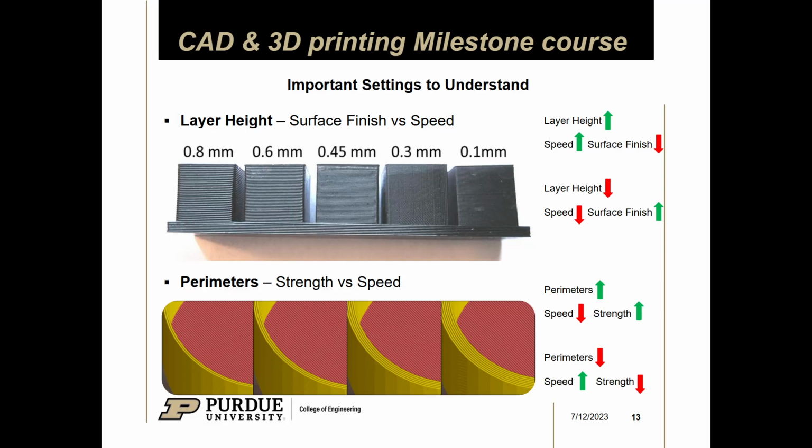So when you're setting your 3D printer to print stuff like that, you're typically trying to find a nice balance between quality and speed. I typically print at 0.2 millimeters, but people print 0.25 or maybe 0.15 or even less if they want more resolution. I found that 0.2 is a nice balance between quality and speed.